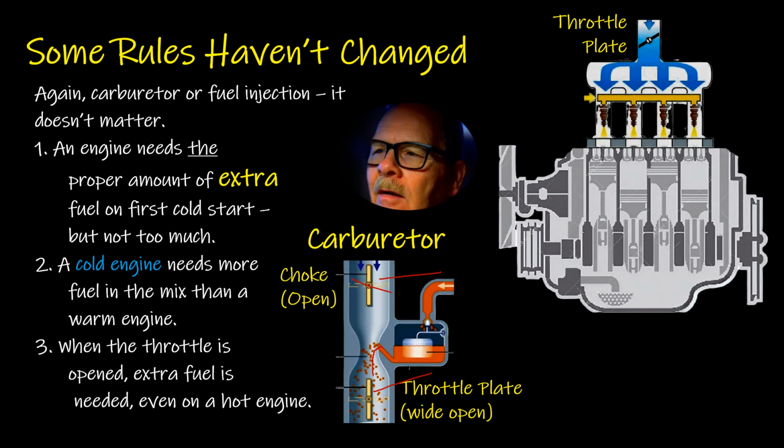But you've got a throttle plate here on the fuel injected engines, and so the fuel goes in there like that. But you're going to have more of that. So when the throttle is opened, just like your accelerator pump, if you're familiar with a carburetor at all, if you've got an accelerator pump that doesn't work, what does the engine do? It just falls on its face, it hesitates.